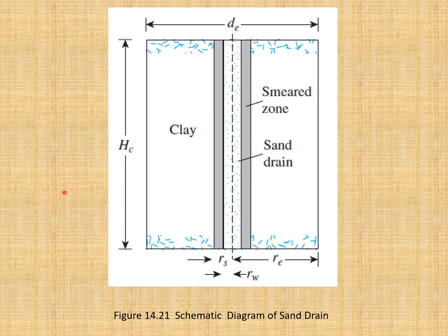One thing that you must keep in mind is that the size of the sand grain also has influence on the extent of the disturbed zone. Or you can say that the smear effect increases with the increase in drain diameter.